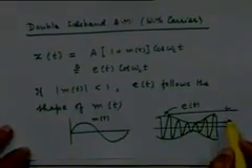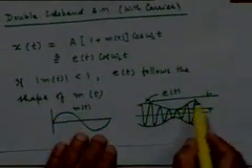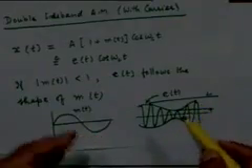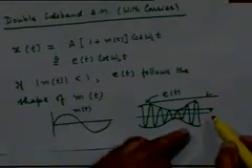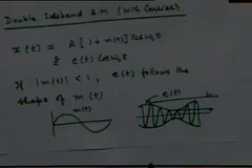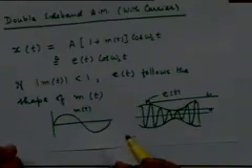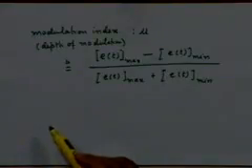In that case, the numerator will be half of this value, which is the one-sided excursion around the denominator, which will be the mean value. So you can think of the denominator, E max plus E min, as twice the mean value. E max minus E min is the total excursion. So half the excursion divided by the mean value is the modulation index. Half the peak-to-peak excursion divided by the mean value of the envelope gives you the modulation index, also called the depth of modulation.